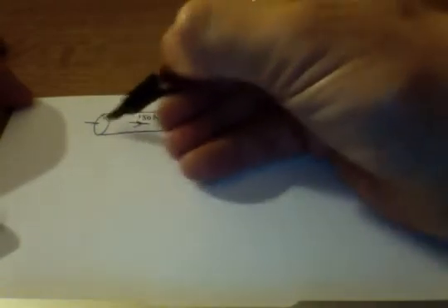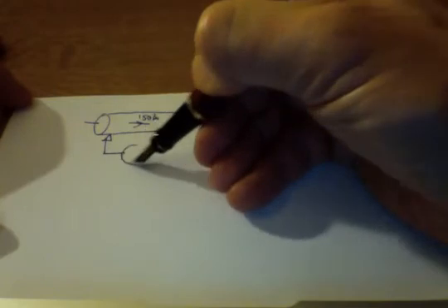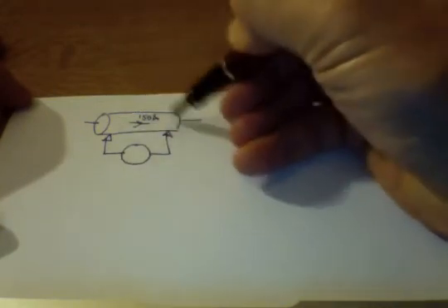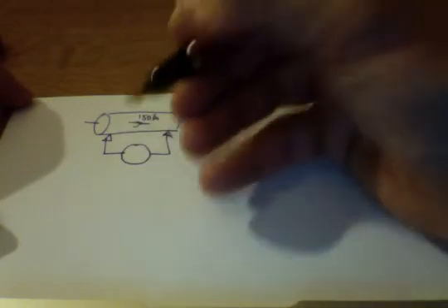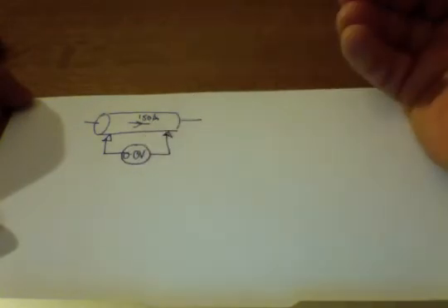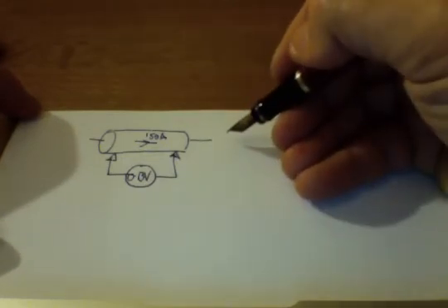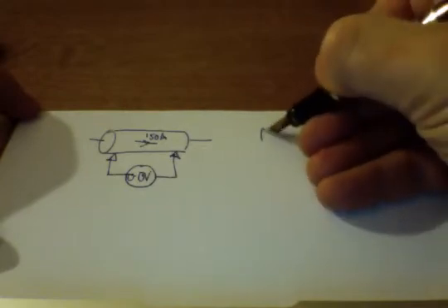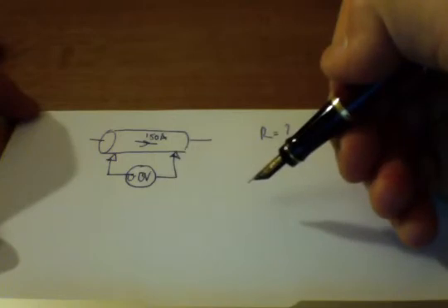And we wouldn't expect any much difference in the potential difference. I mean, it's a little bit weird here because it's not across a battery, but the drop in potential difference, the energy per coulomb lost as it went through this piece of wire, we wouldn't expect more than 0.13 volts across it. So if that's the drop, I suppose the question is, first of all, what is the resistance that this piece of copper presents?